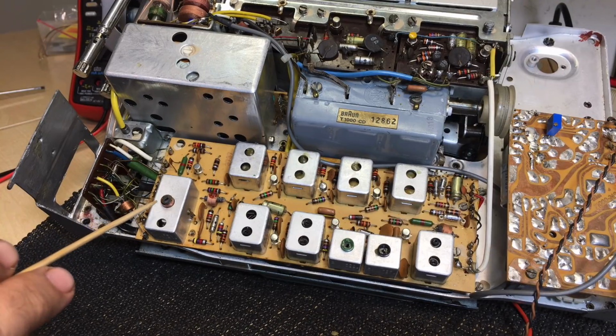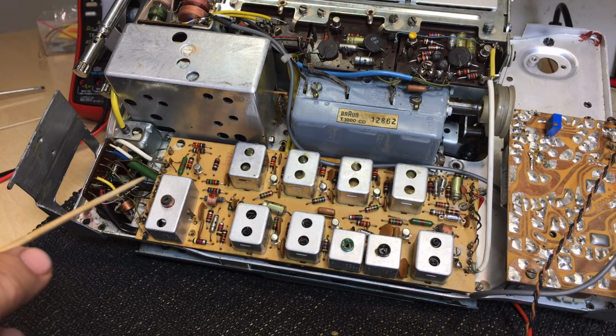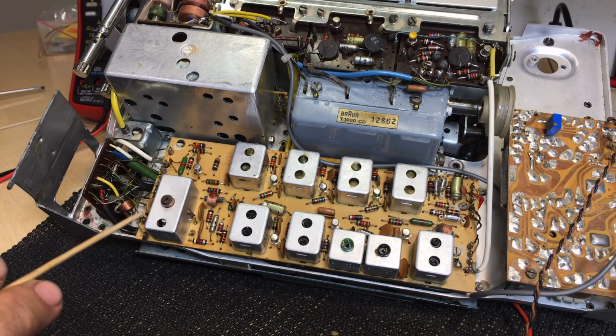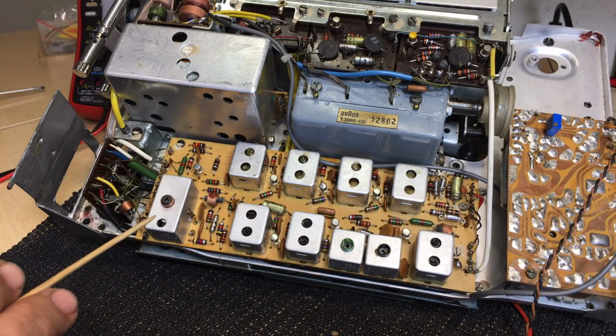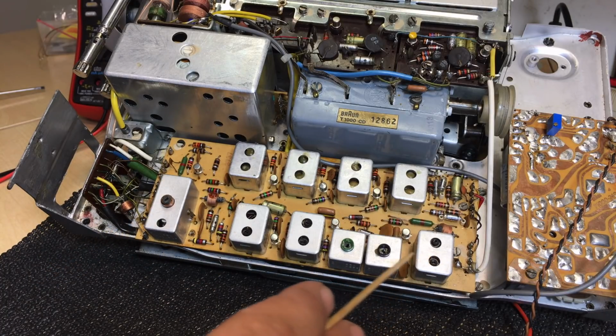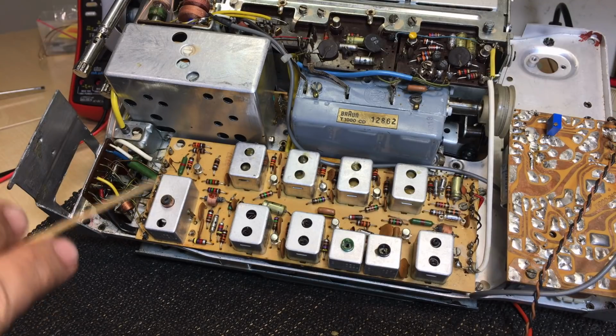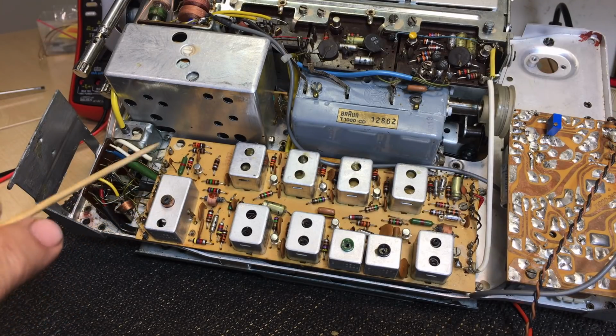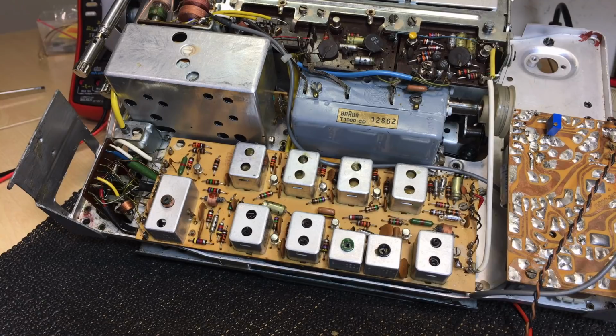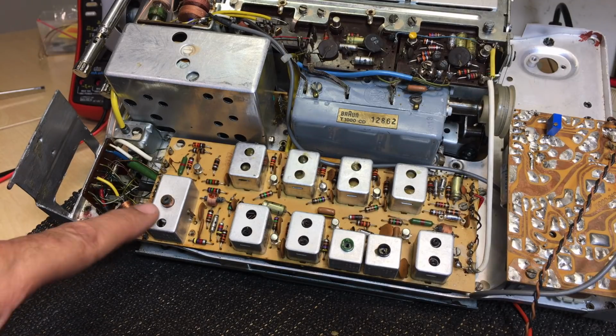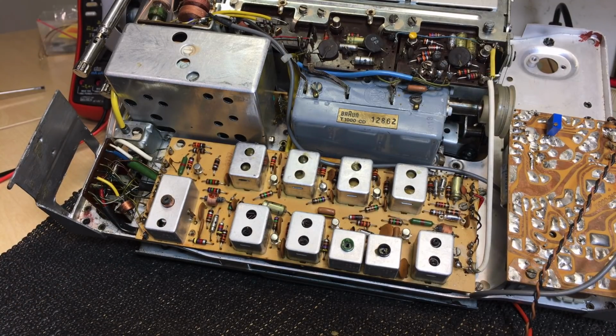It won't be exactly 0, and you can actually adjust it because you will hear the difference. The difference between the IF carrier that you're putting through there and the BFO frequency is going to be, let's say, 2 kilohertz. Let's say this thing is at 453. You will hear a 2 kilohertz whistle coming through.